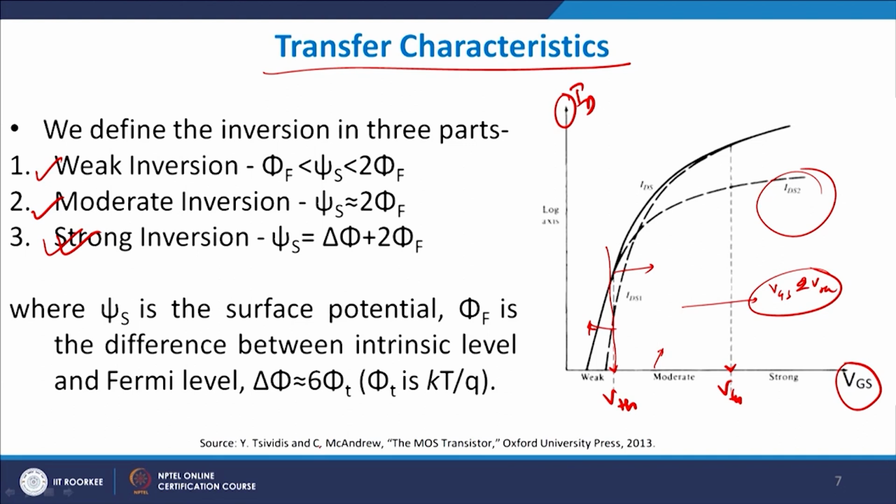So, let us suppose you had a p type substrate where the number of holes were 100. Now, you apply a negative bias. So, electrons are being pulled, they are recombining and the holes are fully removed, fully depleted. So, there are no holes now, you have only depletion available. Now, you still go on increasing the gate voltage, more electrons are pulled there and when it crosses 100, then we define it to be inversion. So, as many holes were initially present, that many electrons are now present. If it is almost double of that, we define that to be a strong inversion. So, I have a weak inversion, moderate inversion and strong inversion.